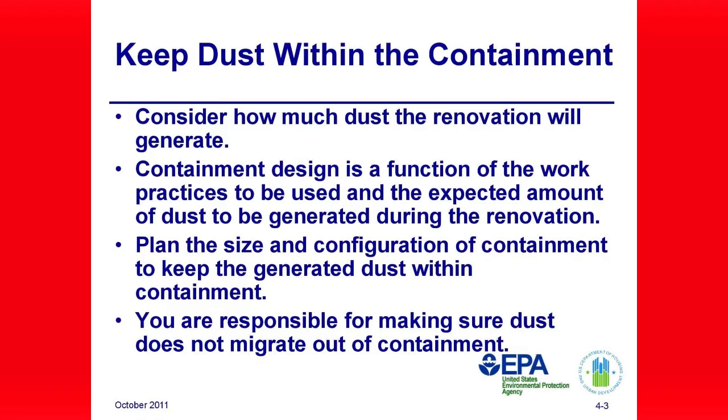Pre-engineered containment systems, purchased or homemade, are very helpful in cutting time spent on the job erecting the containment, and are easier to install than hanging plastic up with tape. These systems also allow the contractor to create a sealed room within a room where the dust can be completely contained for a limited amount of time and within a limited controlled area.